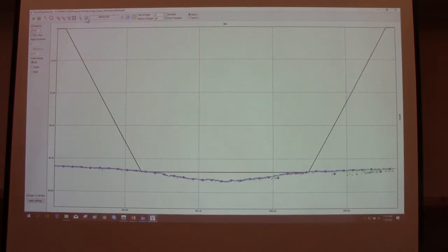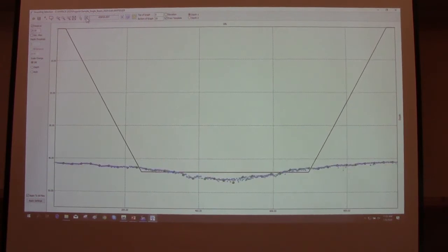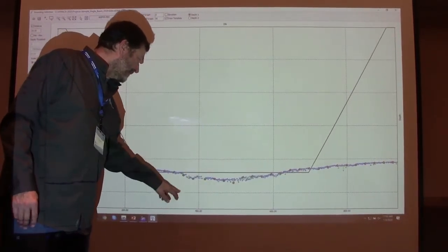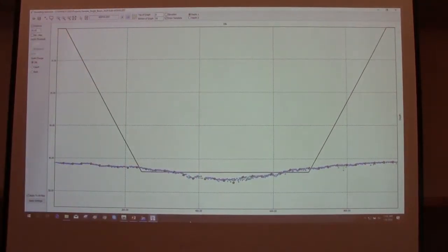Okay. If I want to go back, let me go back to the first one here. And I have a couple, well, it's below the channel anyway, but just say I wanted to save the shoulder sounding here, like object type detection or something. What I could do is, there's a little button right here. It says Select Sounds. If I click on that and go down here, you'll see I could go in there and highlight that. I might want to highlight that and then maybe remove these deeper soundings. So I can click on the button right next to it, undo selection, and then it's going to ignore those and just save those. Okay, so that's one way of doing it.